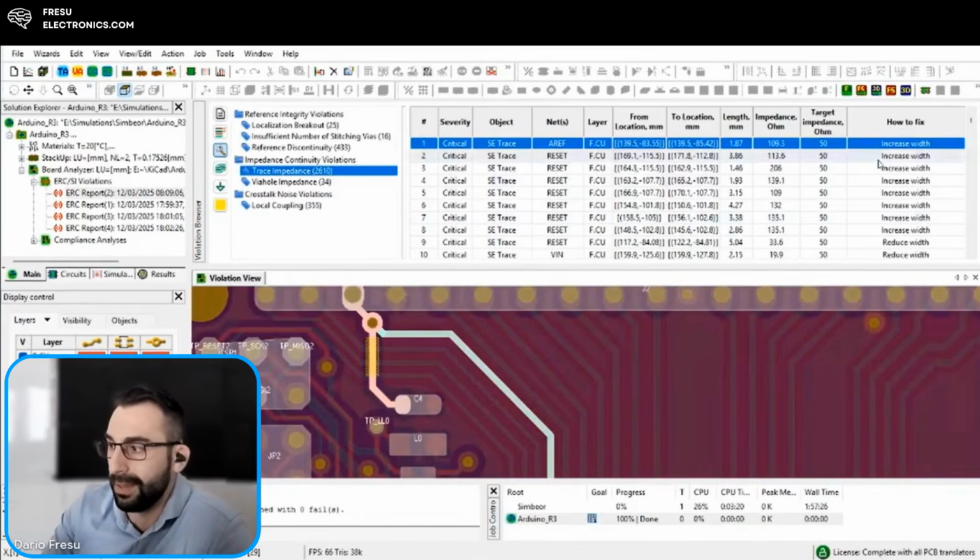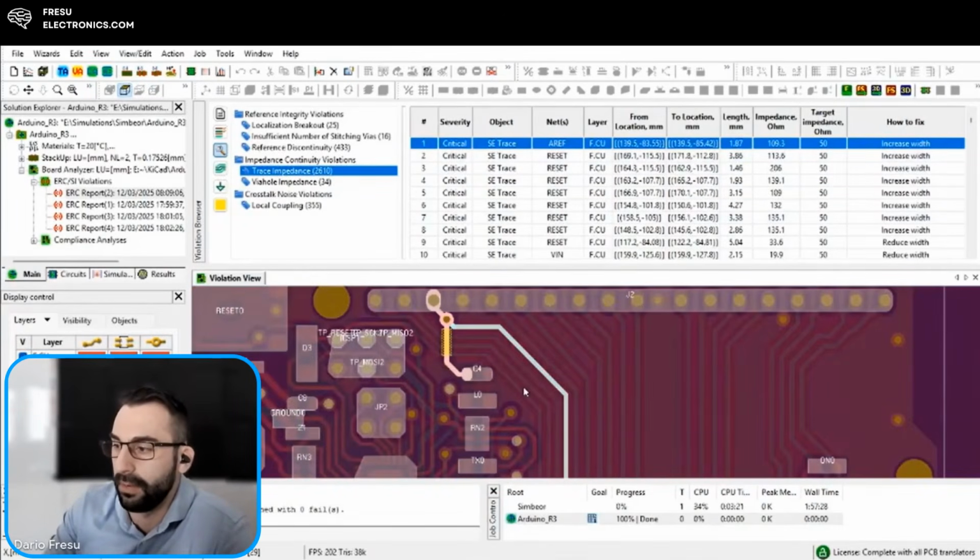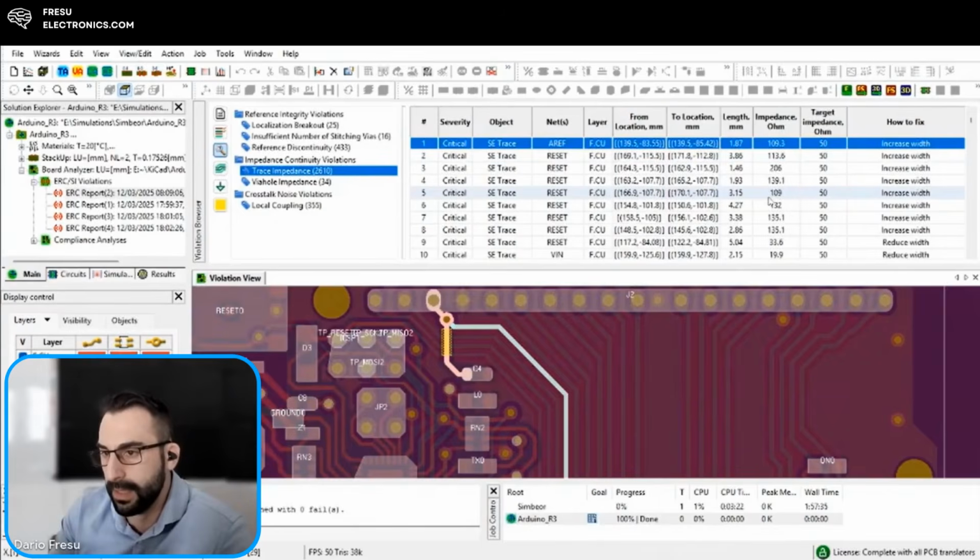So in here, in this case, it's simple. If you use a return reference plane, then you just measure, okay, what is the trace width, what is the distance, and once you put it in the calculator, there are plenty of pre-calculators online, so you can check it easily, or even in this case in KiCad, but even Altium Designer, which, by the way, integrates the Simbeor calculator, and it tells you exactly what is the impedance when you choose the stackup.